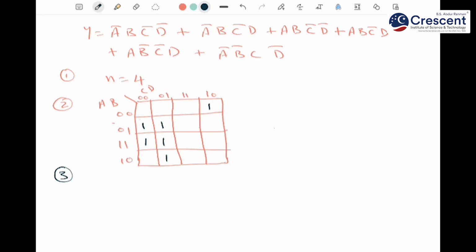So we can give preference to the 4 cells. So here you can take this as one group, and then you can do grouping of this one, and then you cannot combine this with anything else. So this alone is a single group. So these are your groups.